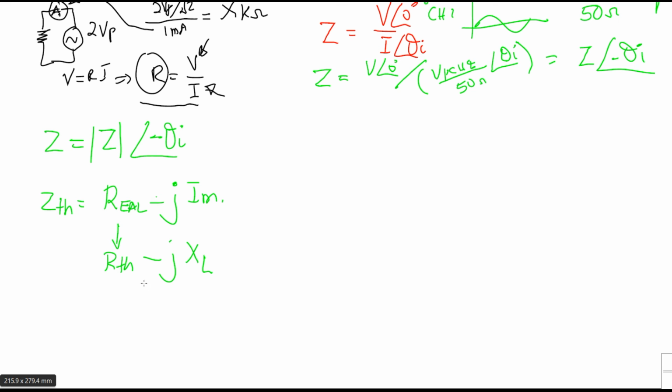Now this R here, if you have a value like, for example, 1055 ohm, and we don't have a nominal or standard value like this, we can use a variable resistor to fix it to this value here.